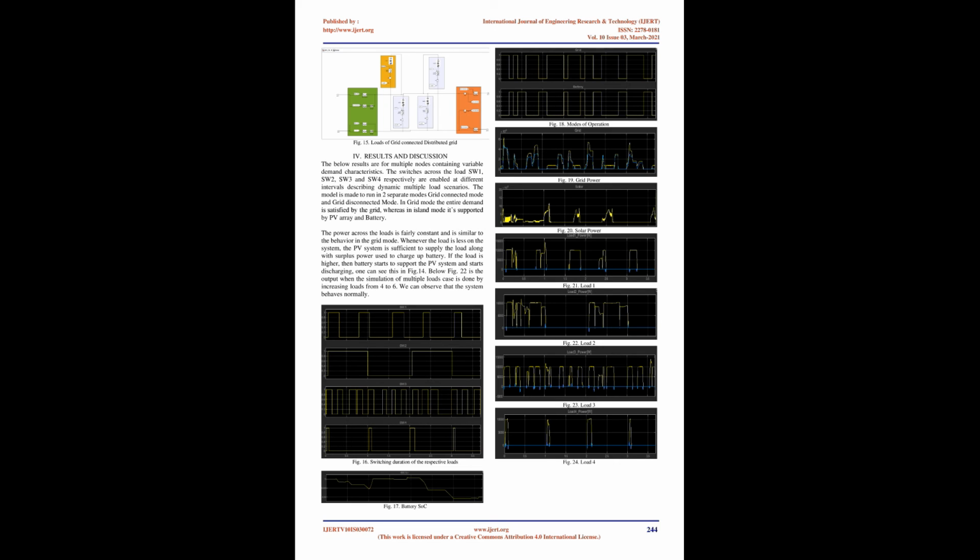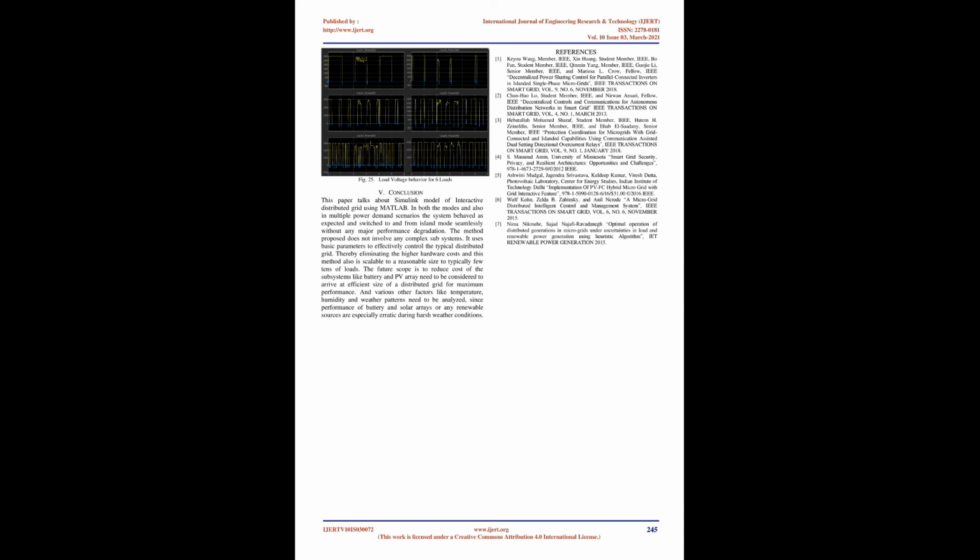Intermediate results. In this simple model, the solar PV supports and recharges the battery as long as the irradiation is above a critical level, as irradiation is directly linked to solar power generated. Whenever the irradiation falls below it, the battery supplies the power to the load. The mean irradiation below which the battery starts to discharge to the load is about 320 W/m2. Above this value, the PV starts to supply the power to the load while simultaneously recharging the battery. Below it, the PV cell alone can't supply the required power and it's substituted by the energy stored in the battery.